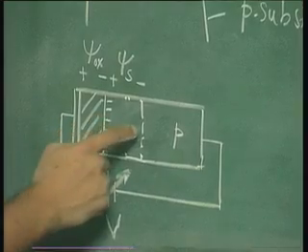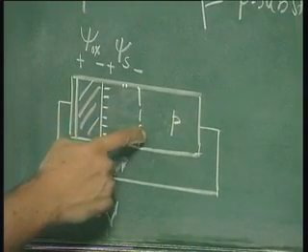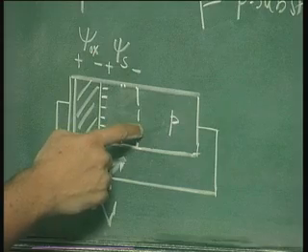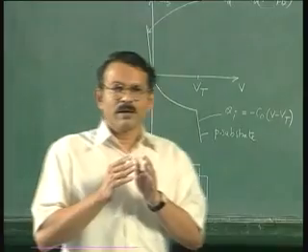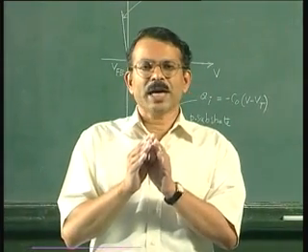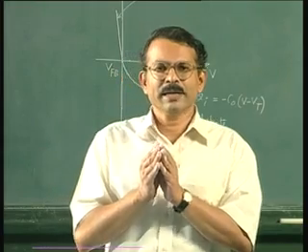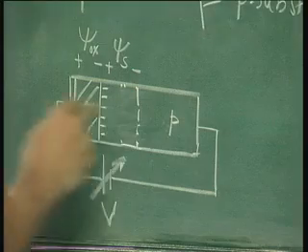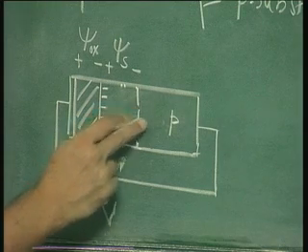Now that change in charge which is required to compensate the change in charge in the gate, that compensating charge in the semiconductor therefore comes from the edge of the depletion layer, because you can change the majority carrier charge very quickly. So you can easily get charges by moving the mobile majority carriers away.